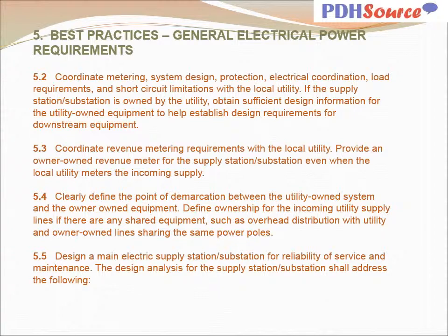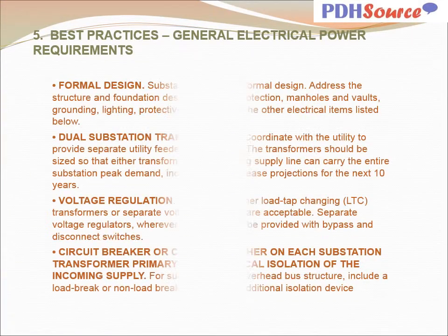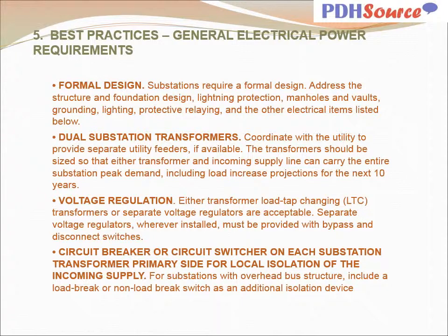Design a main electric supply station substation for reliability of service and maintenance. The design analysis for the supply station substation shall address the following. Formal design. Substations require a formal design. Address the structure and foundation design, lightning protection, manholes and vaults, grounding, lighting, protective relay, and other electrical items listed.